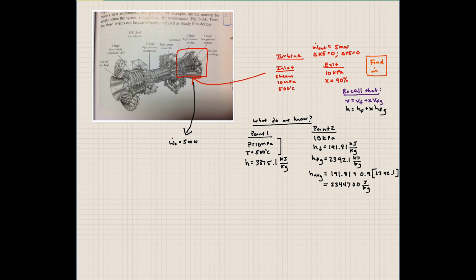So next, the only other thing that we have is the first law of thermodynamics, so let's just write it down. Q minus W. Since mass is the same at the inlet and the exit, I'm going to write here the mass flow rate, and we have a change in enthalpy, since it's an open system, plus the change in kinetic energy, plus a change in potential energy. And we've already stated that kinetic energy and potential energies are the same.